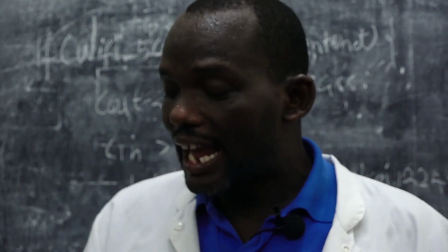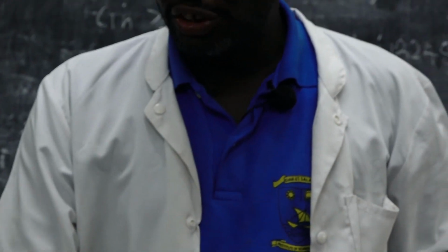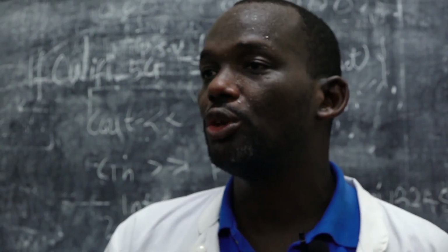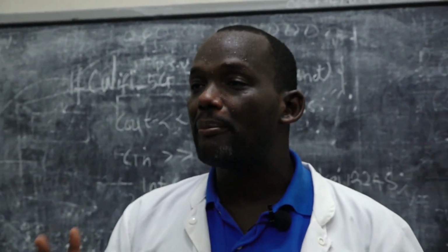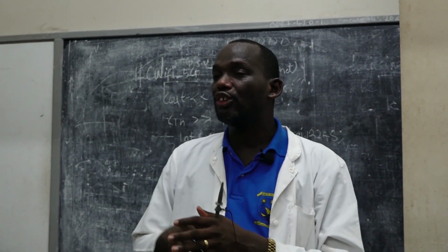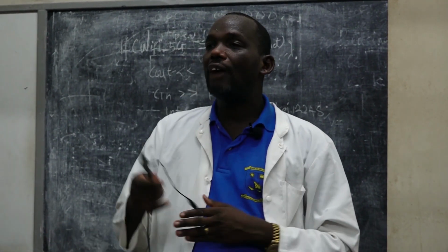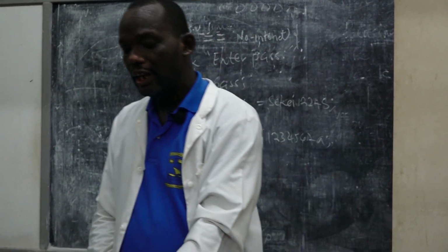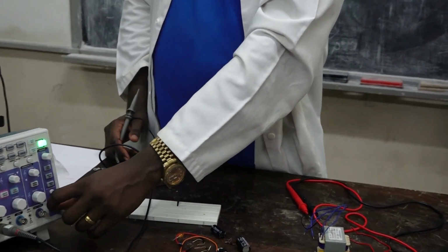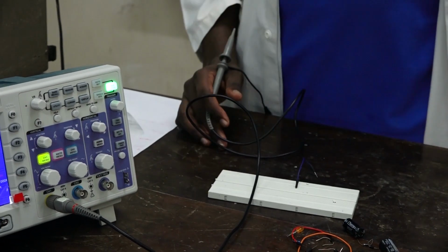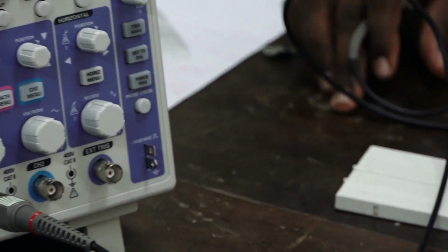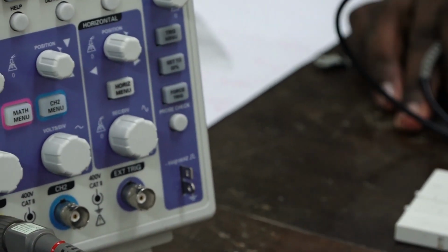And then the next step, which I told you, is that we have to configure, or set, our digital oscilloscope. According to the user manual of this Hantek digital oscilloscope, the manufacturer said that in order to set it, you have to connect this probe into the probe component part. Within this probe component part, there is a circuit acting like a signal generator that can generate the default signal. The waveform of that default signal is a pulse.